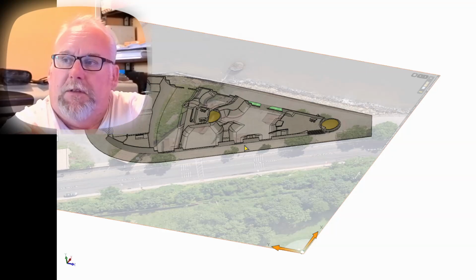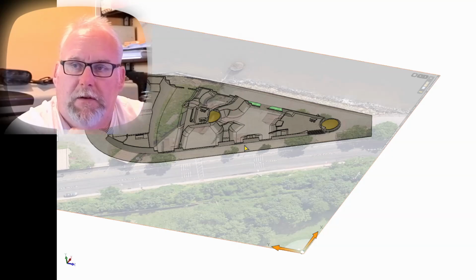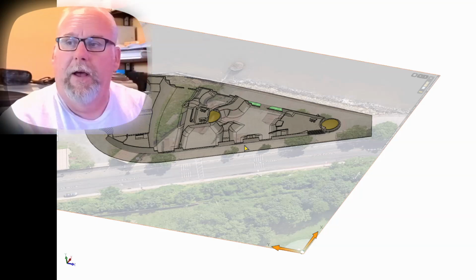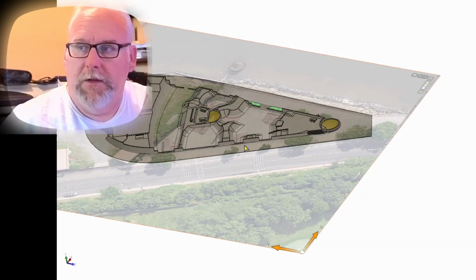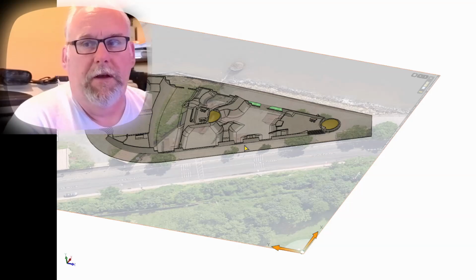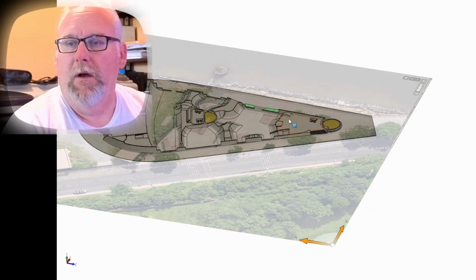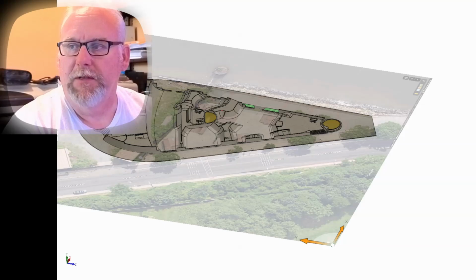because of the river. So the challenge here is you want all your drains, all the surface area in the park to be able to drain out to the river, or you want it to go to the road. I don't know how they deal with their surface runoff, but you certainly don't want anything in the park that's low enough that you're going to have a problem with flooding. So everything in the park is plus, I think, plus 1 foot from the sidewalk. Even the bottom of the bowl here, I think, is plus 1 foot.